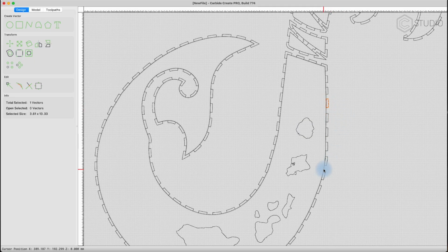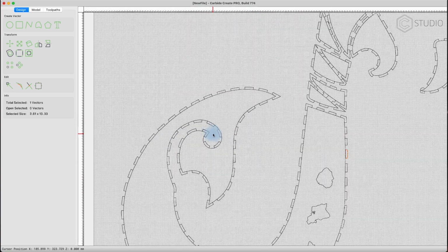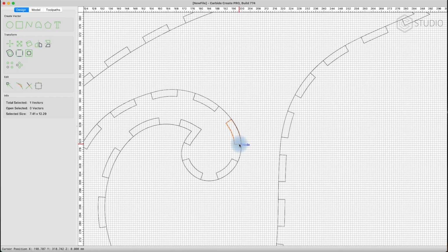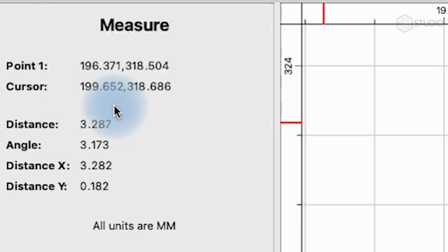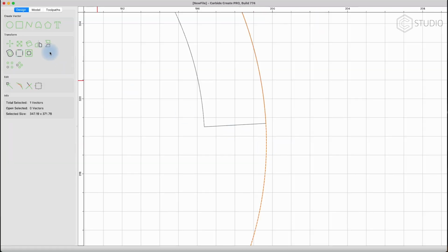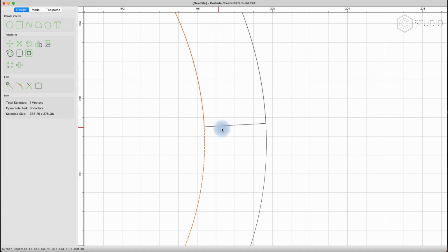Upon import and resizing, it was apparent this hash-marked edge around the design was a challenge. Since this was to be hung on a wall, the ragged edge the original design would produce was not going to work. The first thing I created was an offset path equal to the thickness of those hash marks. By first taking a measurement of the hash mark width, then creating an offset path equal to that number, I created a more complete looking outline.